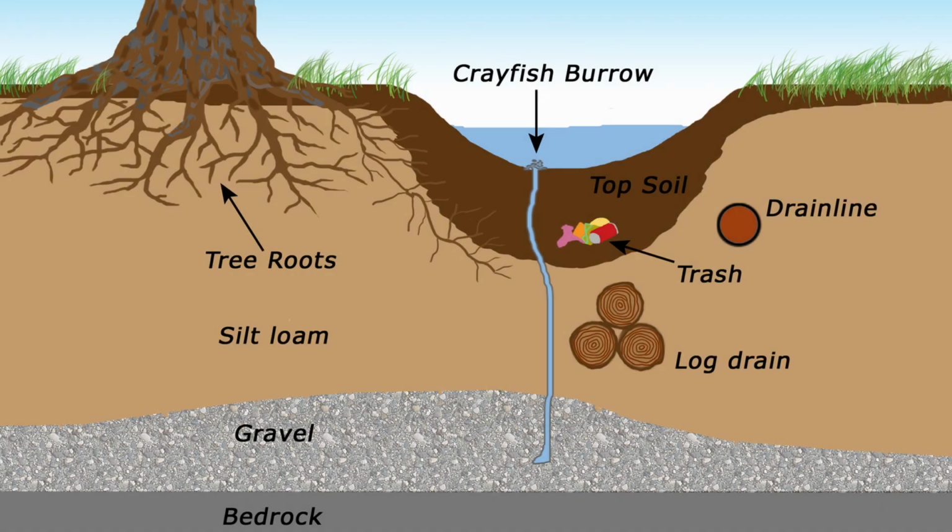This drawing shows why it's necessary to build a groundwater dam when disabling and filling a ditch. The groundwater dam is needed to block the large amount of water flowing underground in the ditch. The subsurface water is traveling in organics and topsoil that have partially filled the ditch over time, and there may be drainage structures that are installed in the bottom of the ditch or along the edge of the ditch.